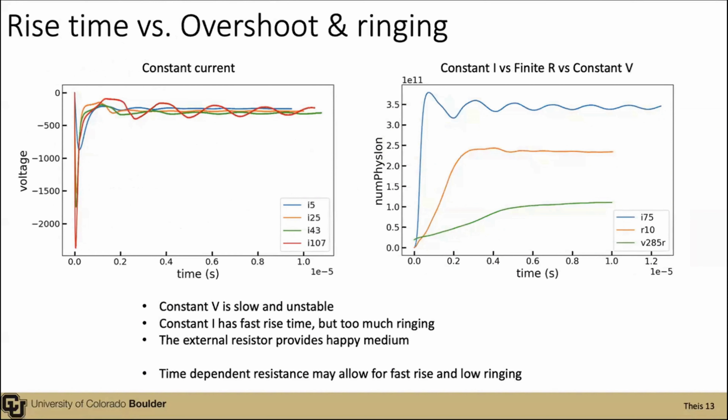Yeah, the next strategy for speeding these things up is looking at the step response of this system to the turning on of the voltage to basically ignite this discharge. And so when looking at the step response of any kind of device, it's all about balancing the rise time and the overshoot and ringing. So this plot in blue on the right shows a constant current simulation where my power source is operating in a constant current mode.